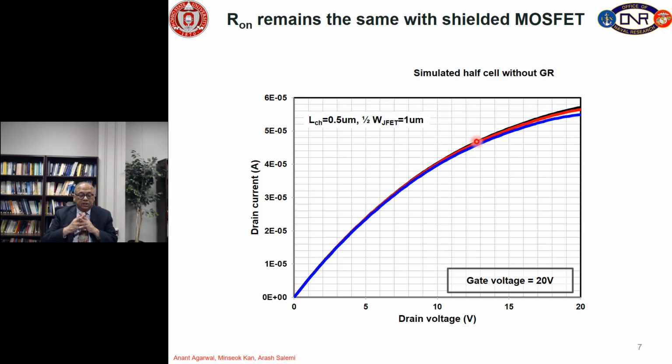And if you see the on state characteristics at low voltage for those two cases, you can see that the forward voltage drop at the operating point in the on state, say at 1.5 volt, doesn't really change. You get the same on state current at the same forward drop. So, there is no negative impact on the on resistance of this device. So, this is an easy fix for this problem, that you can get high short circuit time without sacrificing the on resistance.